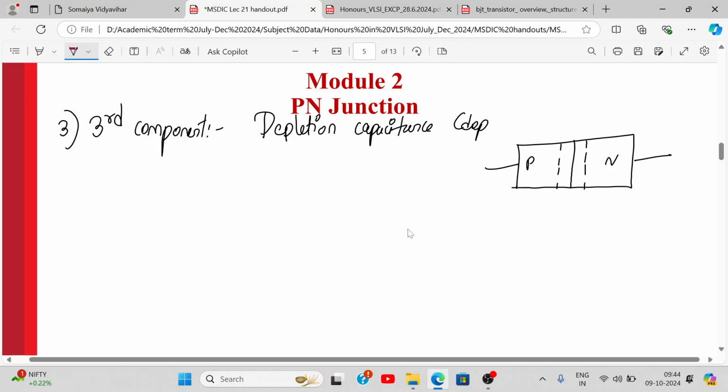Meaning, if I apply a reverse bias to it, like this, and I increase the reverse bias, what will happen now? This depletion region will be expanding, right? That means we are uncovering these charges, right? Yes. So the depletion region will widen. That's the other way of showing that it's uncovering these positive and negative charges, which were not present first.